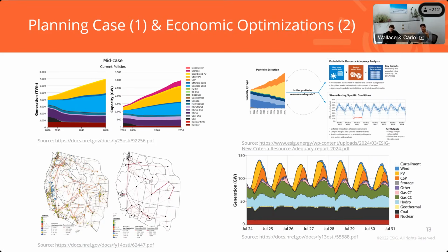So regardless of whether I'm running a resource planning model that has detailed transmission representation, everything we've talked about regarding the need to iterate between resource and transmission planning still stands, and the value I gain from working together with Wallace still applies, because he's going to be able to provide me reliability considerations and constraints that I cannot capture in my resource planning models without him running the more detailed stability studies that he does to plan for transmission and for the reliability of the system.